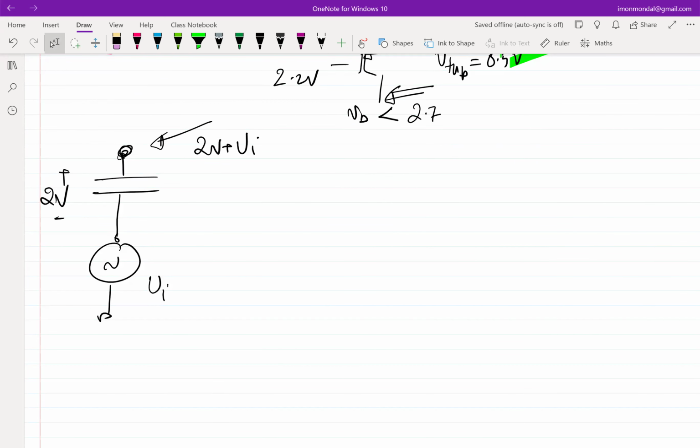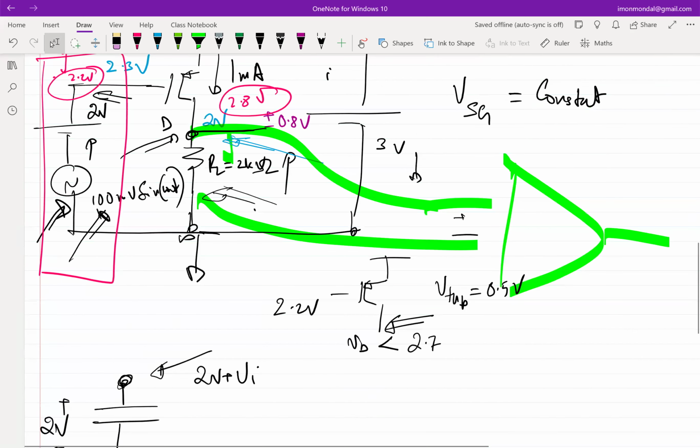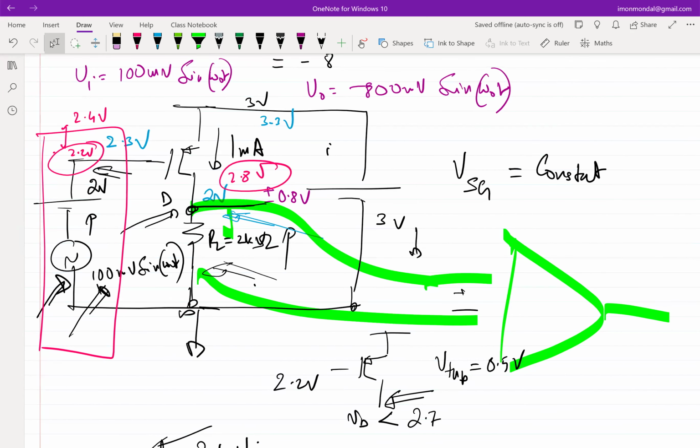But as you must have seen from your experience, it's not like you have a zero-leakage capacitor or zero-leakage circuit. In fact, as it turns out, in modern day MOSFETs also, you have some gate current. So this will not last for long, as you pointed out, which means that we have to do something about it.